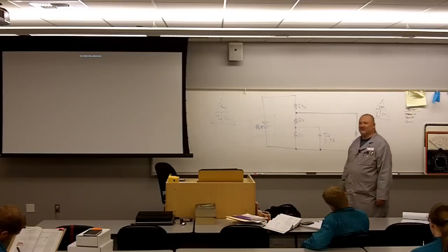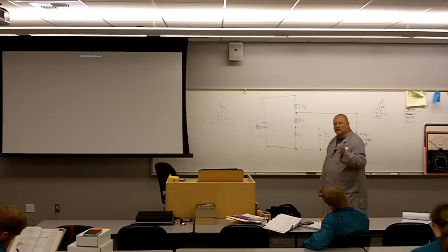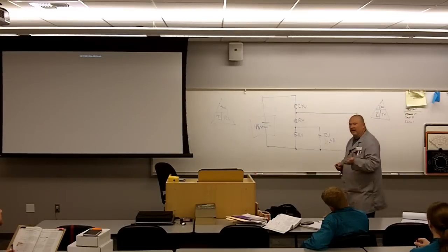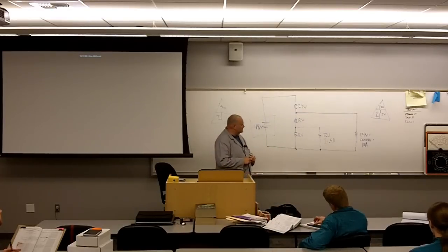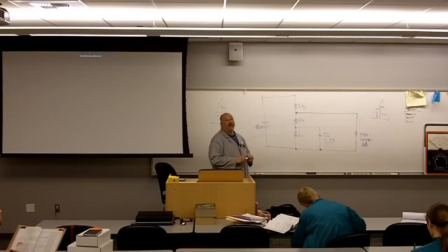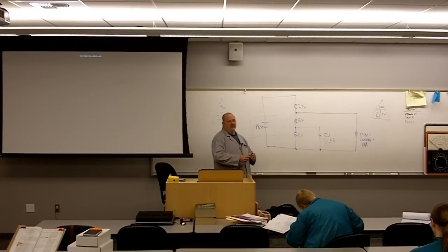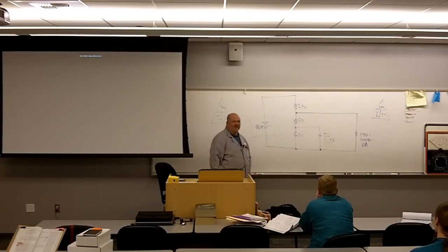Now the question is, what the heck is he talking about, bleeder current? The bleeder current is the current flowing through the first resistor that starts the voltage division process. So by me saying that, first of all, we have to determine what our total load current is. What's our total load current in this circuit? Current is measured in amps. Total load current is 10.5 amps.